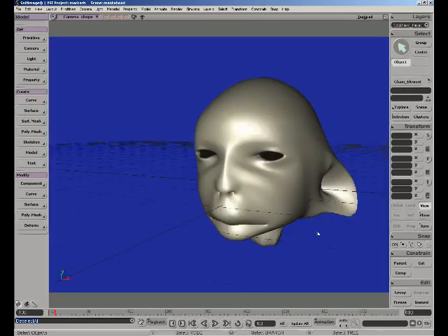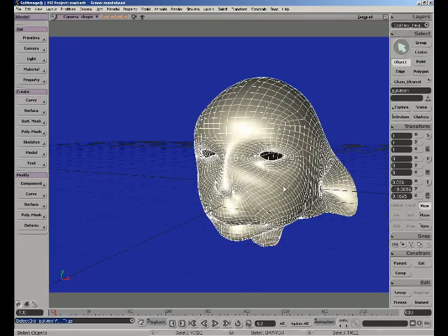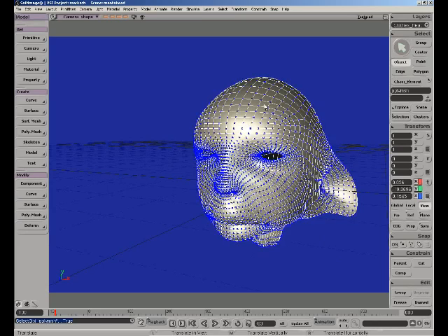We've made a number of enhancements in the area of proportional modeling for version 2. To bring up those enhancements, first select the model you're working with, press the M key. Now that's going to put you in normal move point mode. Now notice here I'm having the normal behavior, not having any influence on the surrounding points. However, if I click on the proportional button on the main command panel, I now have a radius which will show me all the surrounding points that the new proportional modeling command will affect.